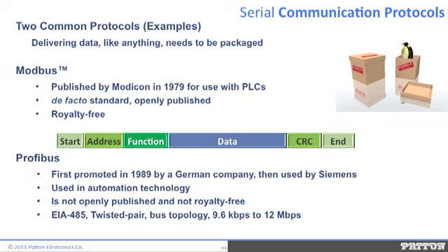The start and end markers delineate the message. The destination address will be identified by the proper receiver, and upon reading the message, the receiver knows what to do, that is the function, what to do with the data relevant to that action. To prevent doing an incorrect action, a cyclic redundancy check, or CRC, is appended to the frame so the receiving device can detect corrupted messages.